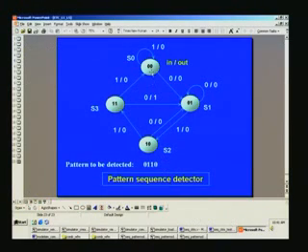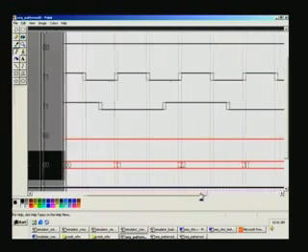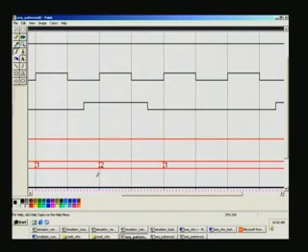We are in S0 state. If it is 0, it should go to the S1 state, right? If it is 1 only, it will remain there. So is that all right? Okay. So where are we now? In 2, at this state. What counts at this state is not this one, but this 0, prior to the positive edge clock transition.